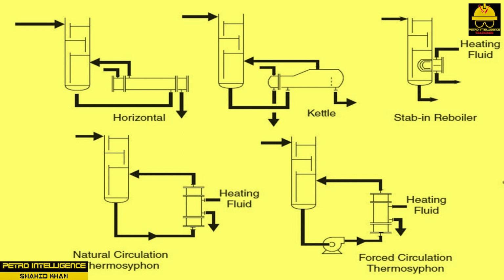Reboiler or steam injection. Reboilers help control overlap and heat balance. Several types and arrangements of reboilers can be used on a distillation column as shown in picture. Kettle reboilers draw feed from the bottom section of the column by gravity flow. An internal weir holds a liquid level over a heated tubular bundle. A vapor disengaging space above the tubular bundle allows the liquid to boil and roll freely and enrich the void with vapors. As the lighter components break free from the larger, heavier molecules, they rise into the vapor disengaging area and exit the top of the reboiler.